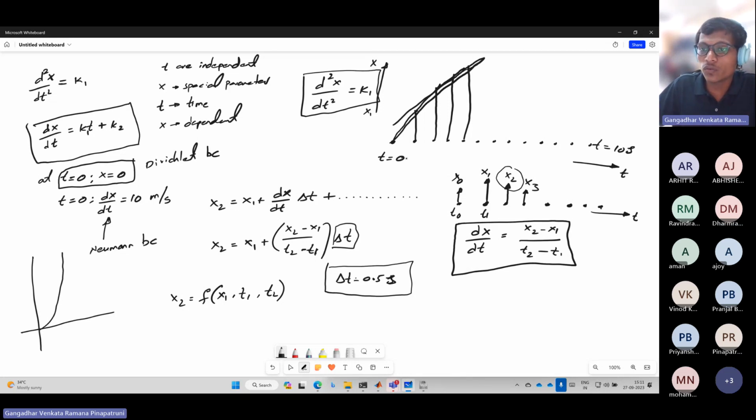In the same way, whatever time we are dividing here, like the same stepping, we are dividing the cell size. The cell sizes also act like this. If you divide the cell size to be very, very small, you will get a much more accurate solution. If you use a coarser one, with a very large stepping, like only one or two cells, then you will get a very bad solution, or maybe an improper solution also. Okay.